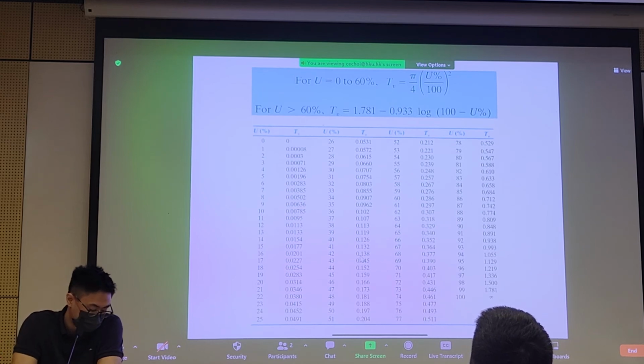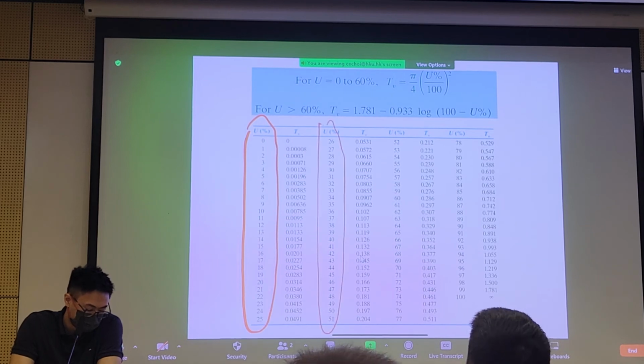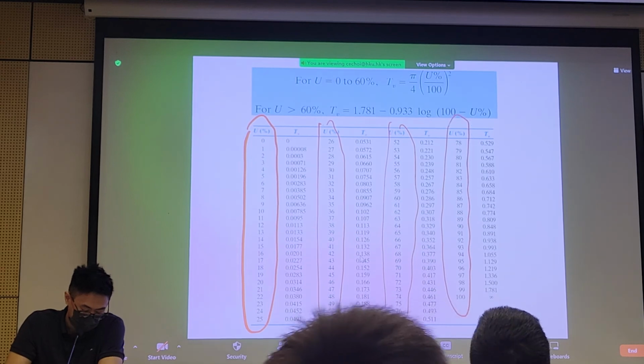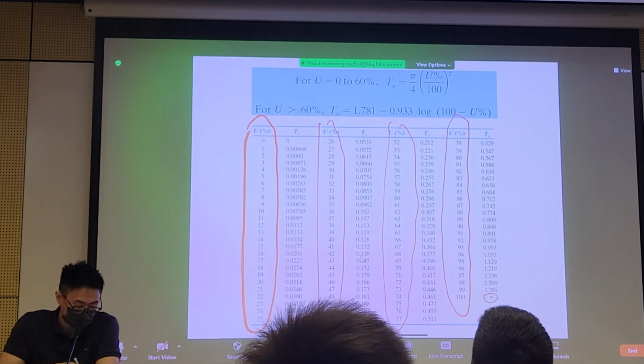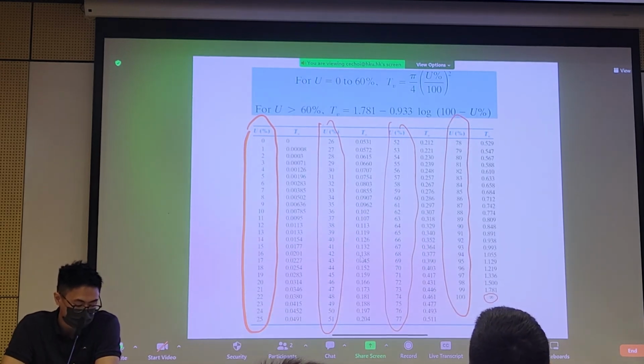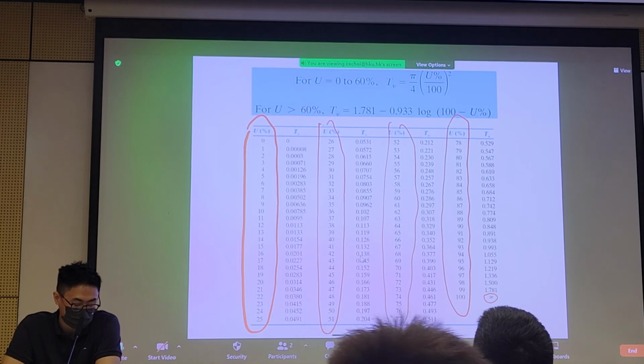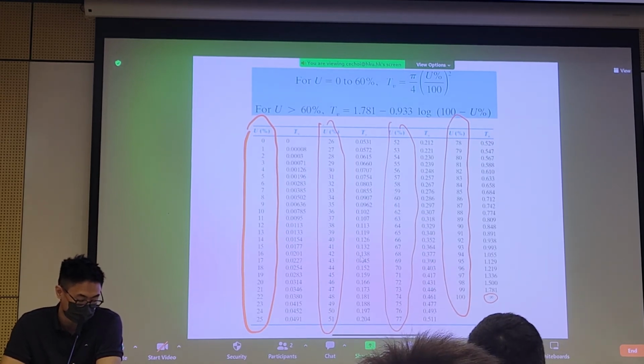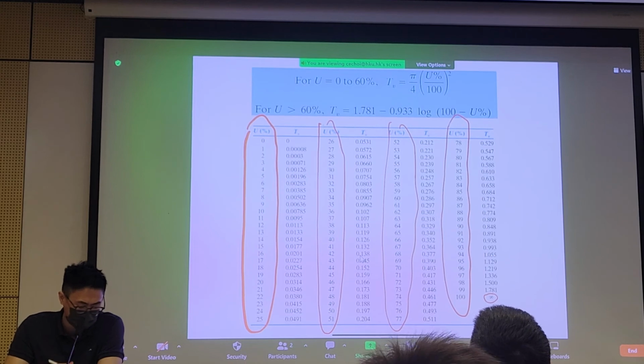You would just look at this column here. This goes all the way to 100, right? These columns. And your time factor would be infinity here, but based on your known degree of consolidation, you can extract some time factor. Right now it's quite abstract, but when we start doing questions together, you'll understand where all these graphs are coming from. So we often just use graphs to get the average degree of consolidation based on time factor relationships. Now, we'll come back to this in a bit.